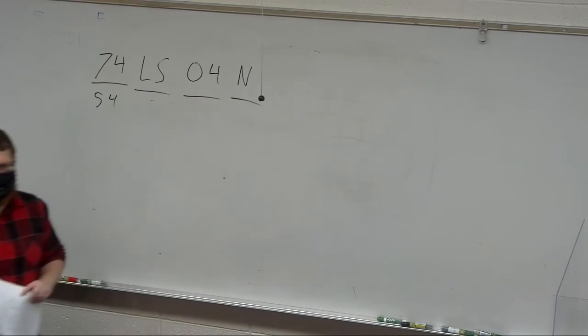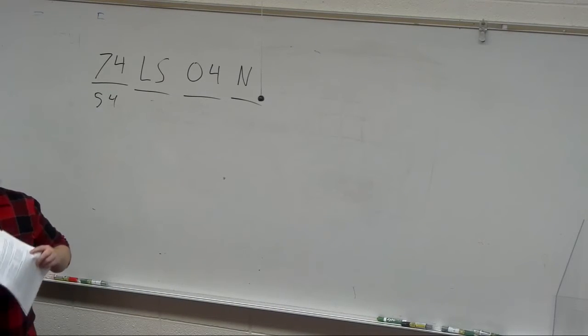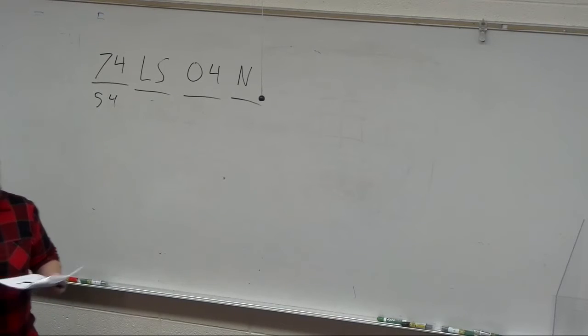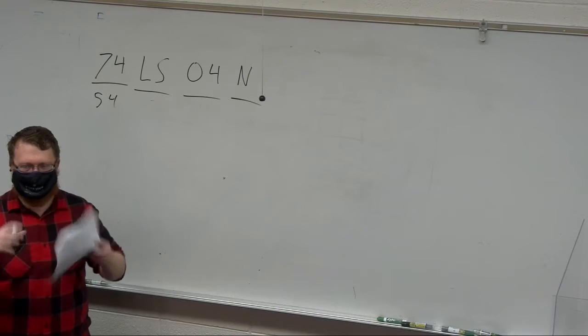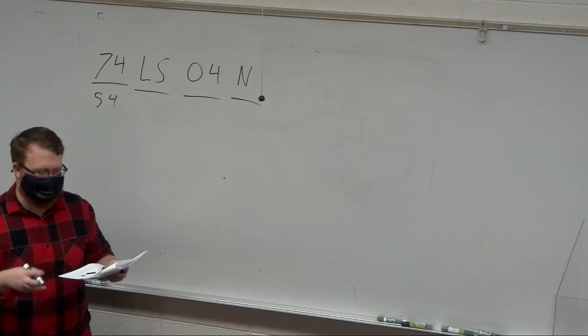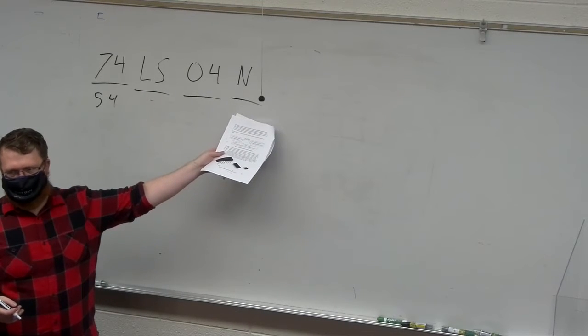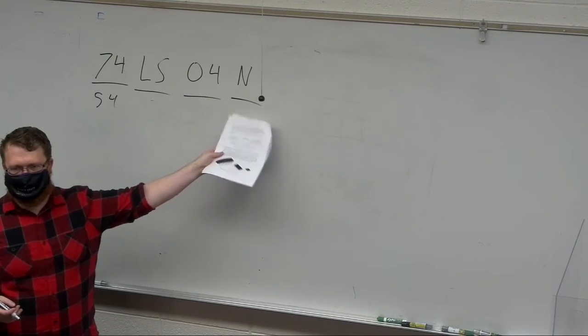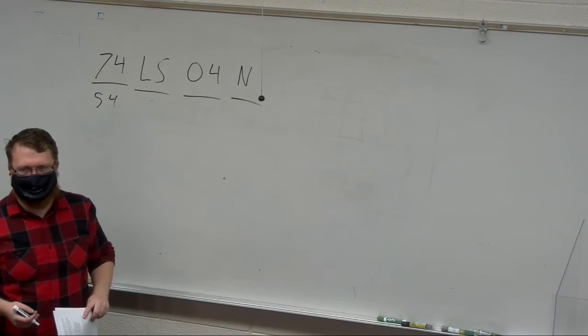Lastly, the N is the package, right? It's what the plastic bits are containing, all of the actual digital logic. So the N is what we're using, which is parts designed to plug into breadboards, right? They're the DIP.